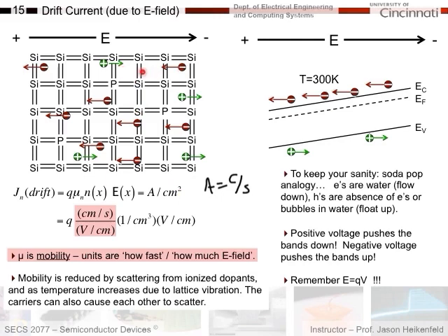So you can find electrons, as they're trying to move in this direction, start bumping into each other. A good analogy for that is a highway: as you increase the number of cars on the road, at some point their mobility decreases and you get a traffic jam, because things can no longer move forward in an orderly fashion. They're in danger of running into each other. And in the semiconductor system, they start running into each other just like you sometimes see on a crowded highway. So that's how we calculate our drift current, which is caused by electric field.